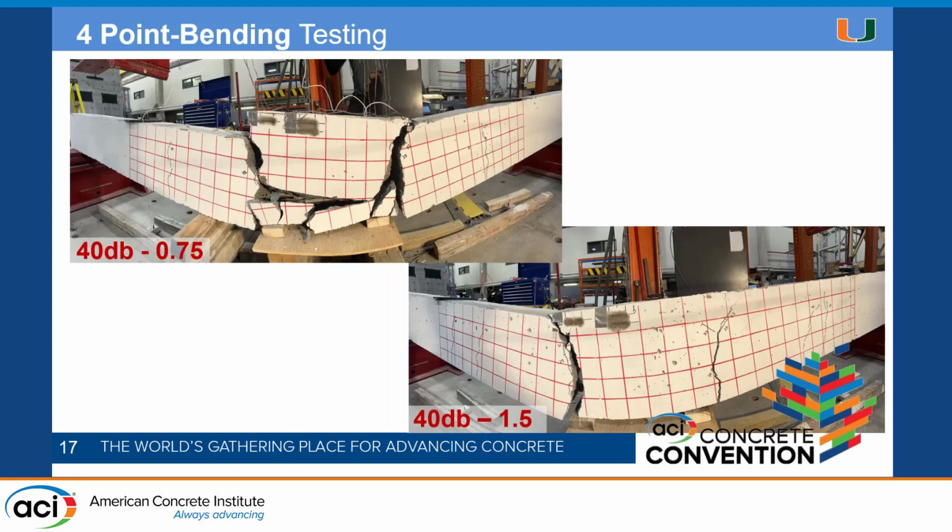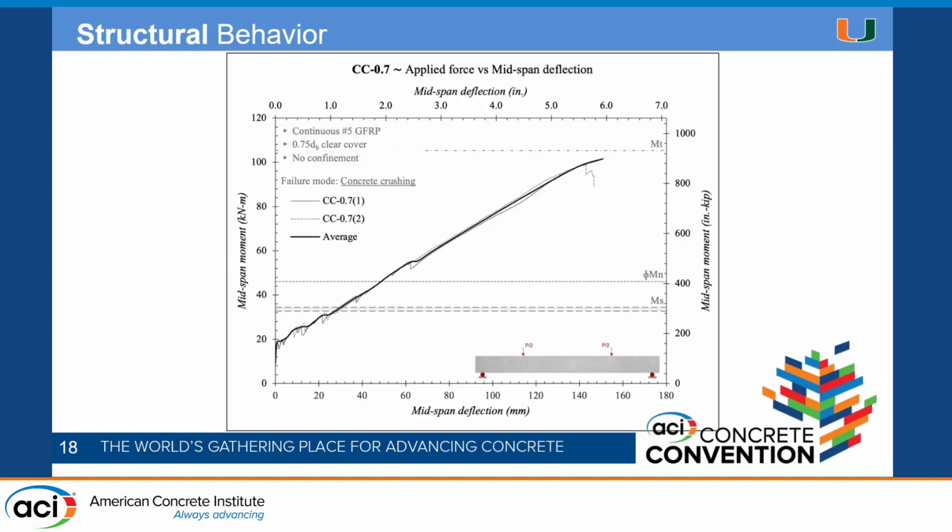So we want to classify both, because the current equations are only based on the splitting failure mode. Usually the slippage failure modes are avoided in the requirements by establishing a minimum embedment length, and the splitting failure, which is a more complex process, is handled with the equations.